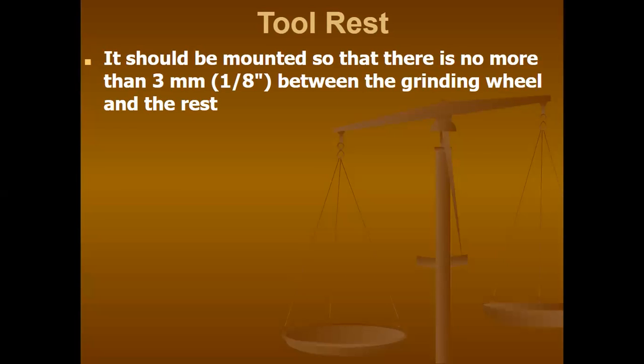I do allow students to use gloves on these pedestal grinders, but what they must do is use a pair of locking vice grips to hold their material, so that way their hands are an adequate distance away from the rotating stone. Because that stone is rotating in a downward motion, it's going to pull your glove in. If it grabs into your glove, it's going to pull your finger in, and bad news will happen.